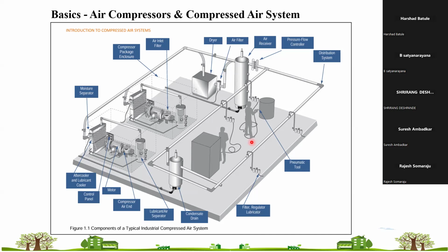That moisture need not flow through the system, because any moisture in a pressurized system will cause more corrosion. In a steam system also, you will not carry wet steam, but will require dry saturated steam at your user end. It transfers heat more efficiently than wet steam. So those are some of the phenomena.